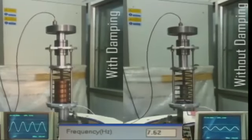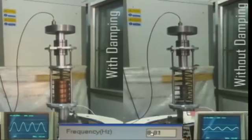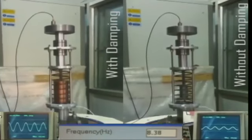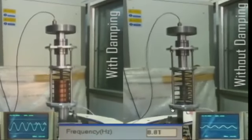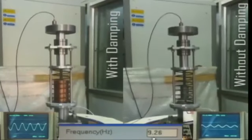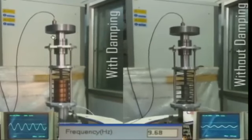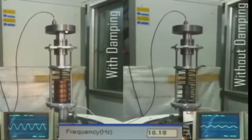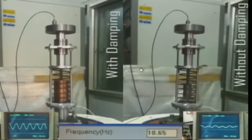In this case, the specific damper is called an eddy current damper, and the frequency of damping is around 8 hertz. So, it is between 7 to 8 hertz level that you would see it. As you increase the frequency, you may come across a situation where this will be even more vigorous here. On the other hand, with the damper there will be hardly any, as I told you that the damping is very important close to the resonance.